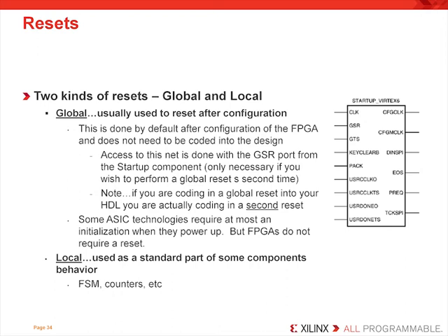For most designers, a global reset is not necessary, but for some, especially ASIC designers, it is essential that they can emulate this behavior. To help give them access to this reset, Xilinx provides what's called a startup block for both Spartan-6 and Virtex-6. These components allow users to drive an input signal onto the global set reset net at any time and reinitialize the FPGA at any time. The benefit is that since there are so many resources that have to be connected to such a net, Xilinx has embedded this routing delay inside the silicon. This saves designers from having to route the signal on general interconnect and then consume valuable routing resources.